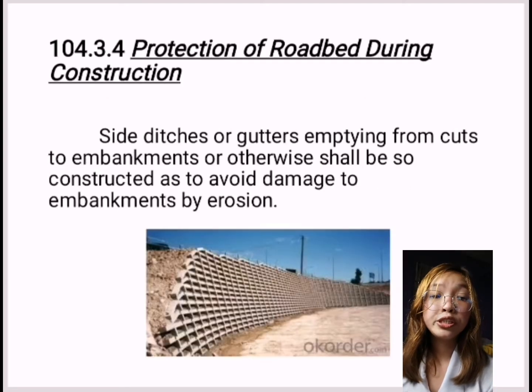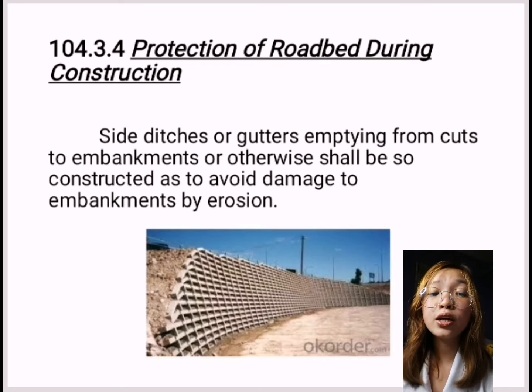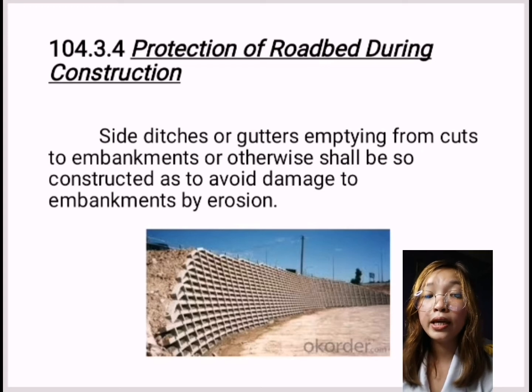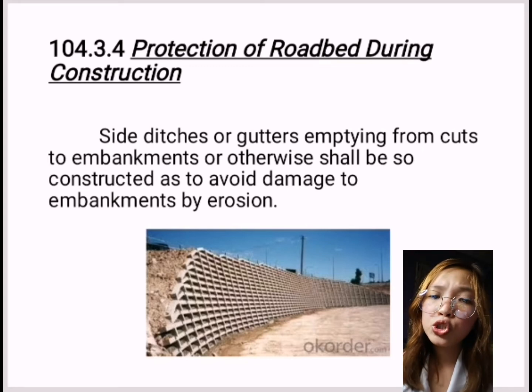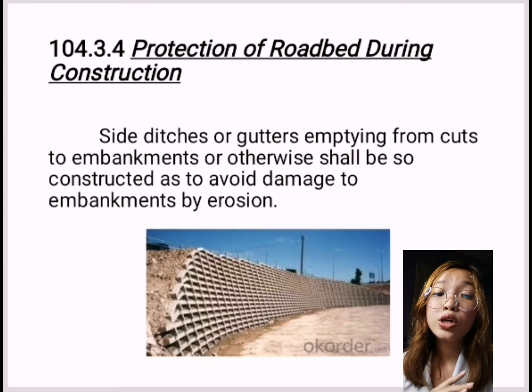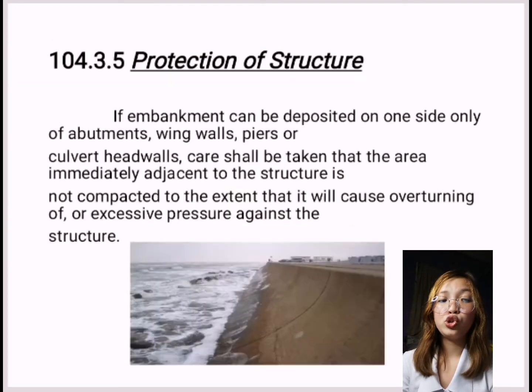So now let's proceed to item 104.3.4, or the protection of roadbed during construction. So during the construction of the roadway, the roadbed shall be maintained in such condition that it will be well drained at all times. Side ditches or gutters emptying from cuts to embankment or otherwise shall be constructed so as to avoid damage to embankments by erosion.